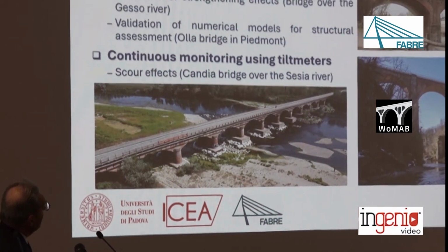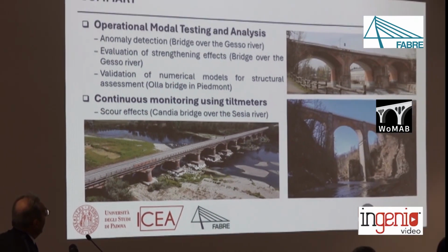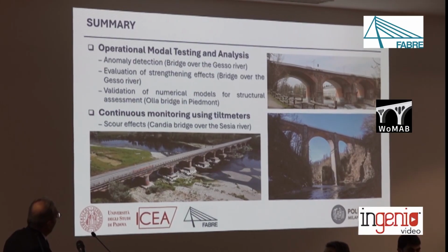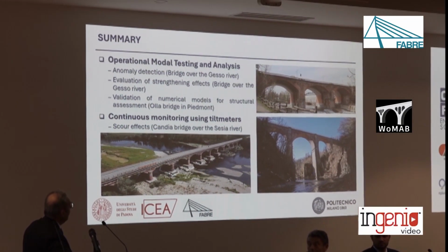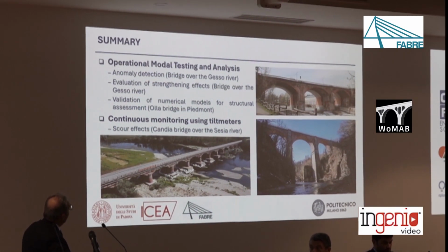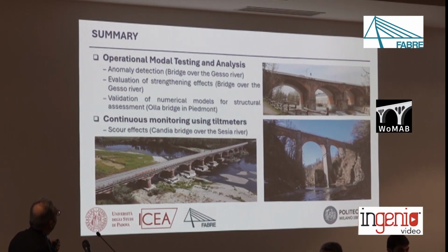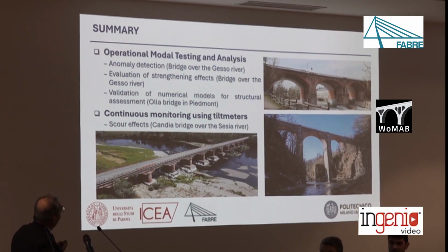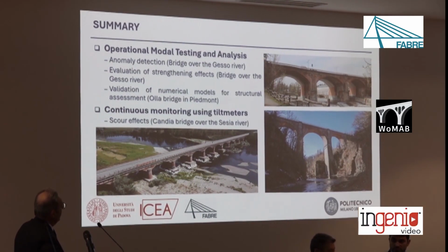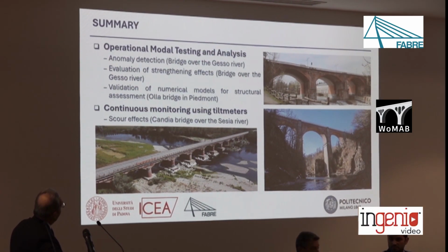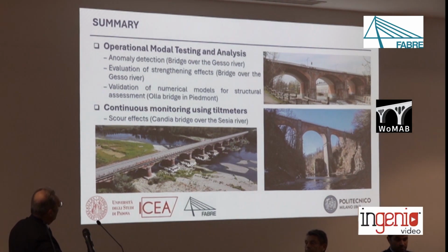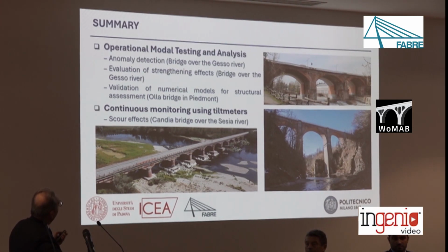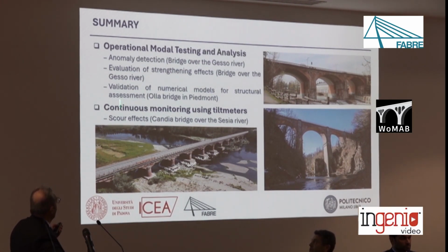For the first 2, on your right-hand side, we have performed the operational modal analysis, testing and analysis. And the results I will show include the anomaly detection and the evaluation of strengthening effects for the first bridge. For the second one, operational modal analysis was a key step in the validation of a numerical model for the structural assessment of this second bridge. Both these bridges are in the province of Cuneo.